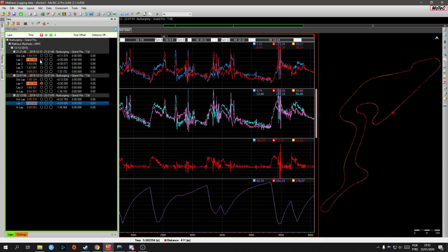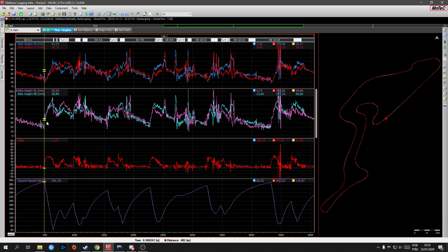I was more looking into making a car comfortable to drive using different wing configurations, and that car generates a lot of downforce even at lower speeds. So it has a big difference pretty much for the whole track, especially for the fast turns, like let's say the Schumacher S, which is really high speed. You see over 200 kilometers per hour. So in those corners, you really want to pay attention to your aero balance, which I'm going to talk about later.